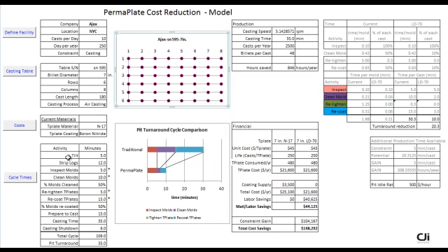So now that we've established that information, the model then, based on parameters that we've input, will calculate speeds, times. It will also take the values for the cycle times, and it will compare between the current, in this case, the N17 versus the LD70, and then it computes the potential turnaround time reduction. In this case, it's 20.3 minutes, which is reflected in this graphic, which shows the basic elements of only the turnaround that is variable, and that is the inspection, the cleaning of the mold, a very small bar here for retightening of transition plates, and then necessary recoating.